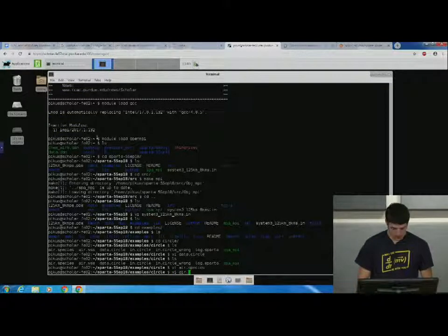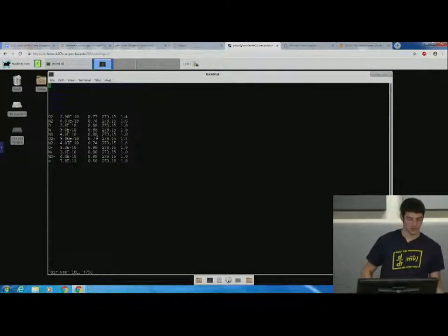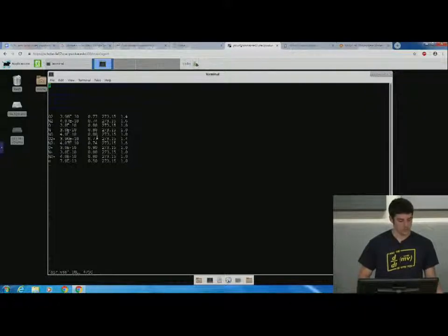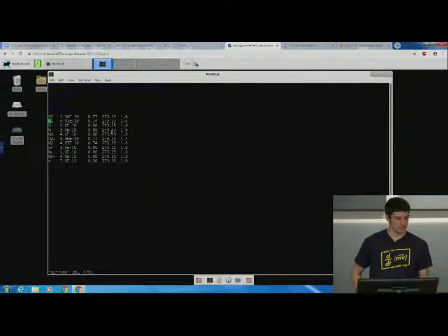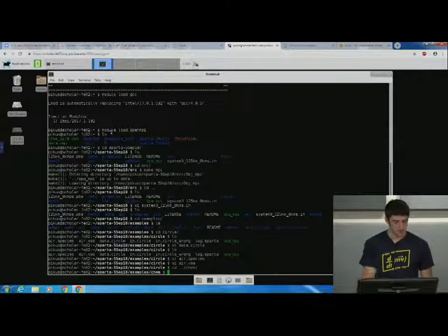Then there's the VSS file. This is according to the collision model. And the important thing here is your diameter, your viscosity coefficient, and well, here they have the reference temperature, which is again important for the viscosity coefficient, and your alpha. And that's again specified all here. So as long as you're just using these molecules, you have nothing else to worry about. You can just keep using these files. So this case example doesn't have chemistry, but they have an example called chem that does.